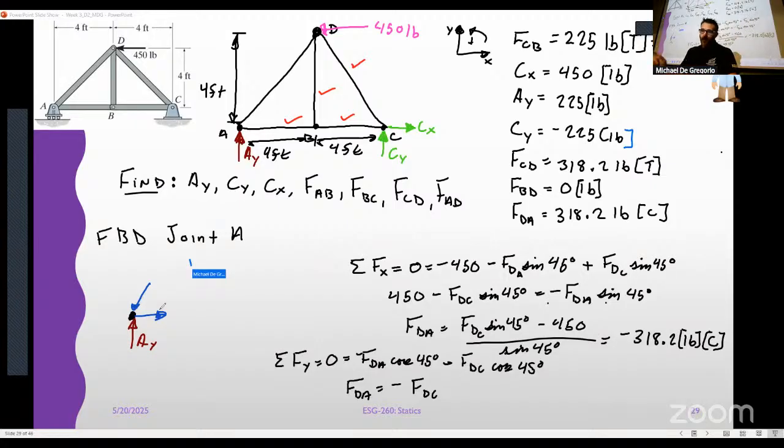Okay. So anytime you solve a joint, if you find out that it needs to be in compression instead of tension, the next joint where you see that force, flip it. Draw it the way, because now you have knowledge of it. When we don't have knowledge of it, we assume tension just because that's the standard convention. You can certainly do everything assuming compression. That's fine too. But your answers will look slightly different than what mine do. Just heads up.